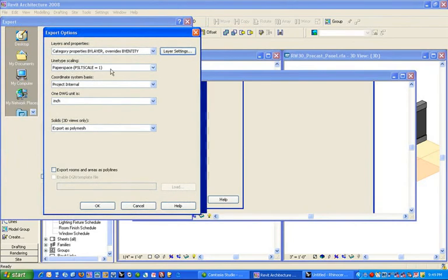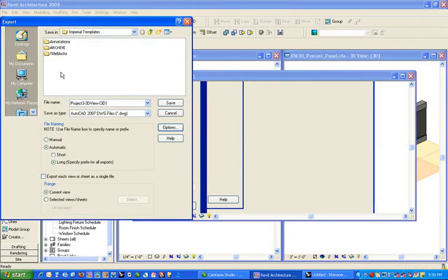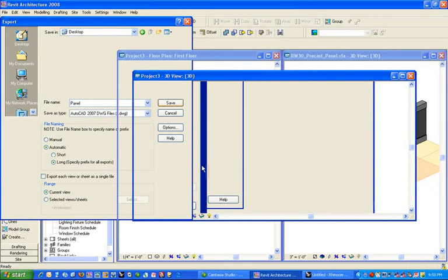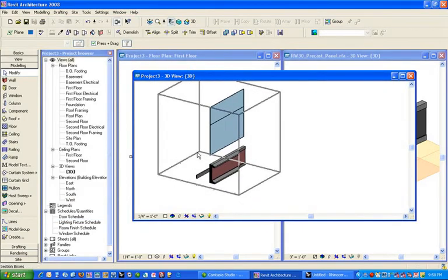Line type scaling for CAD drawings. We'll use the project's units, and this is the system units. But really what all that spiel was for is this. Export as a polymesh or export as ACIS solids. We'll do ACIS solids, which is NURBS, or closed NURBS. And I'll just export it out to the desktop for now. And we'll save that out. And then let's do that again with the polymesh.